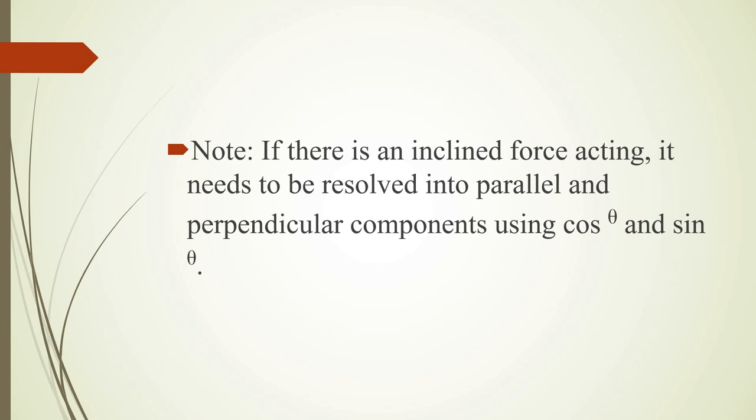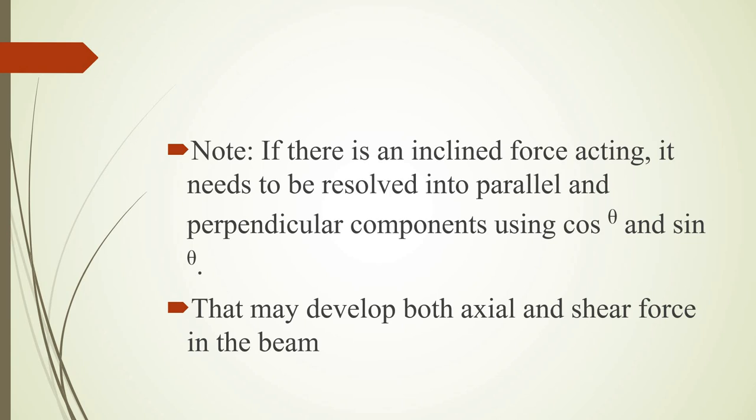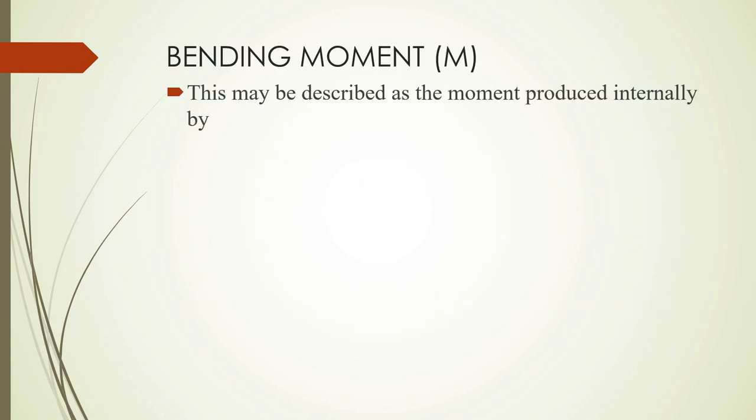Now we talked about parallel forces and perpendicular forces, but if you have an inclined force, it's going to be resolved into parallel and perpendicular components by using sine theta and cosine theta. So if there is an inclined force, that's going to form both axial and shear force in the beam.